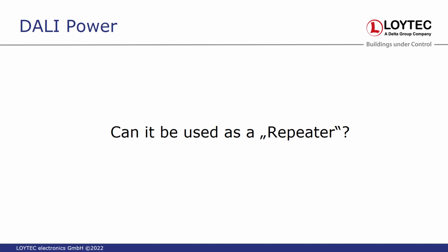The power supply only puts in the power. When you have a longer channel, there are actually DALI repeaters out there, which would be on the channel and would really refresh the signal, and you would have a galvanically separated channel. So then you would really need a DALI repeater, but you cannot do this with a power supply.